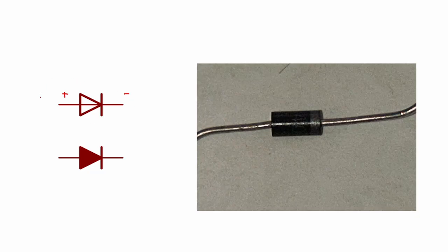And so how do we tell which of these is which on a real diode? So here I have a picture of a diode, and if you notice, there's a very hard, kind of faint silver band right there. That silver band is analogous to this little chunk here. So this is the positive side of the diode, and this is the minus side of the diode. If you hook that in that direction, so you have the positive side of the circuit over here and the negative side of the circuit over here, it's forward biased. If you put the positive here and the negative here, it's reverse biased.